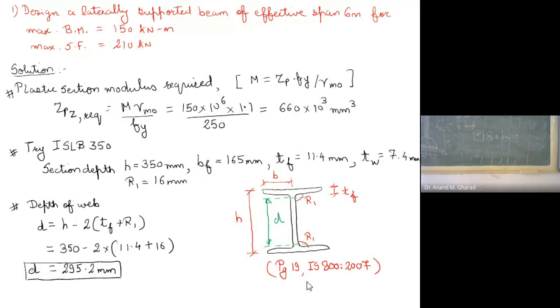Acha, before this, how many types of bending are you aware of? If I take the example of any beam, may it be simply supported or continuous, how many different types of bending do you know? Have you ever heard about simple bending or plain bending? Simple bending. What could simple bending be? Bending only in one direction, correct? Okay, and that bending which takes place either in the principal, major principal or minor, that is simple bending.